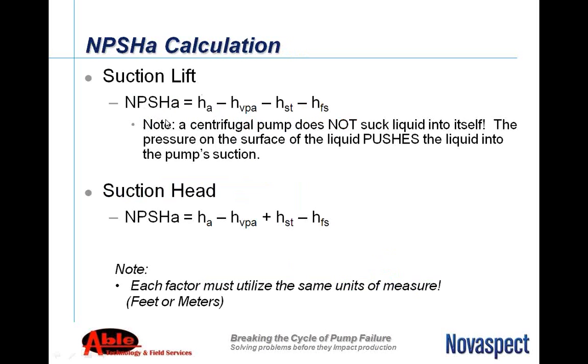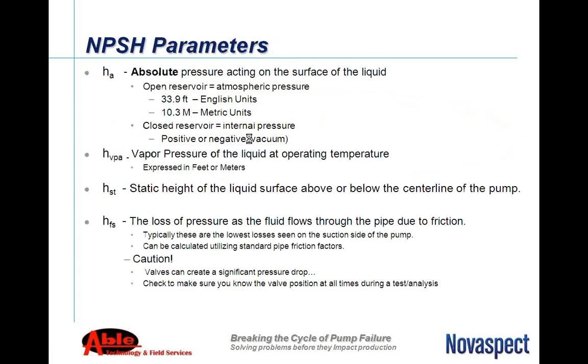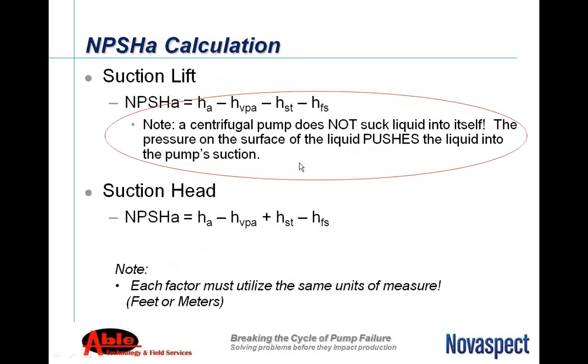For the calculations, one reason I just put the screen up is that I don't want to go into a great deal. I'm not going to bore you to death with functions or calculations here. But the note is right here: a centrifugal pump does not suck the liquid into itself. That's the key thing you need to know. The pressure on the surface of the liquid actually pushes the liquid into the pump suction. It's very key to understand.